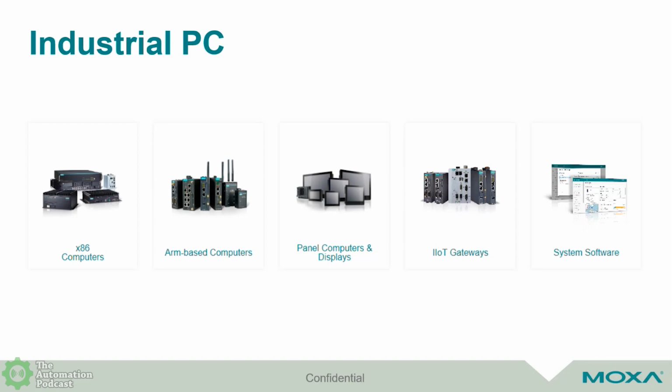Today, before I start, I'm going to give you a little introduction on the industrial PC, what it is, and how it is different from a PC that you and I use at home or work on, at our home office or for personal use or for business. So industrial PC or an IPC or industrial computer, these are different terminologies we use. These are basically a rugged solution designed to meet demanding environmental requirements, such as protection from liquids and dust, extreme temperatures, and some high shock and vibration applications. Sometimes you have EMI all over the place where you're using this device.